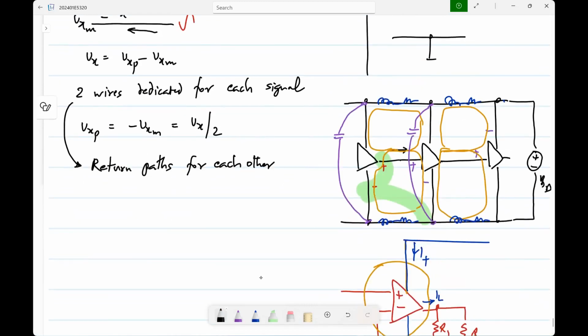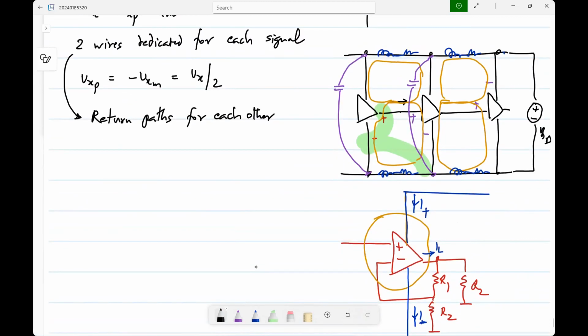So for instance, if you just have two wires crossing each other, in cross section it may look like this. This wire may be on a higher layer and the other wire may be on a lower layer. Now, of course, you have parasitic capacitance between there and there, and some parasitic capacitance from there to there.